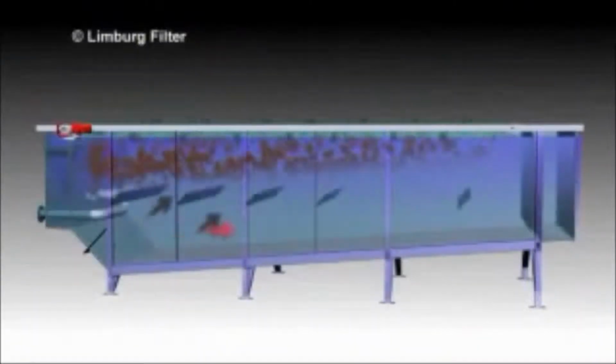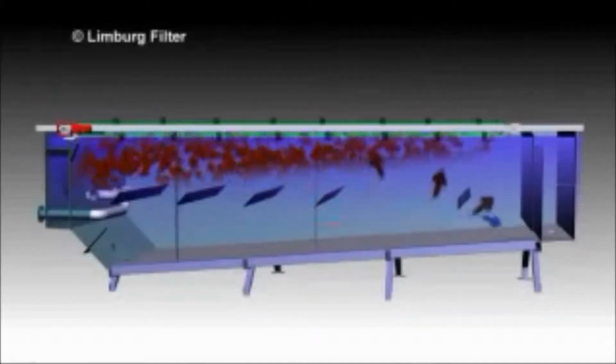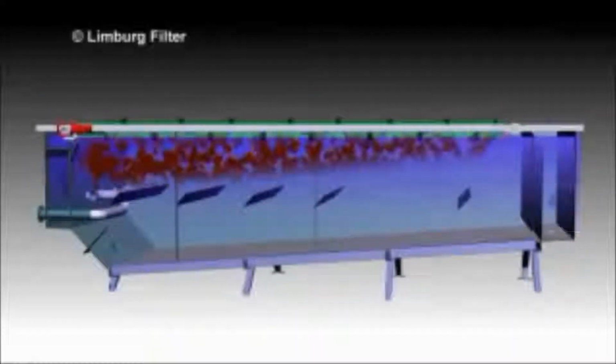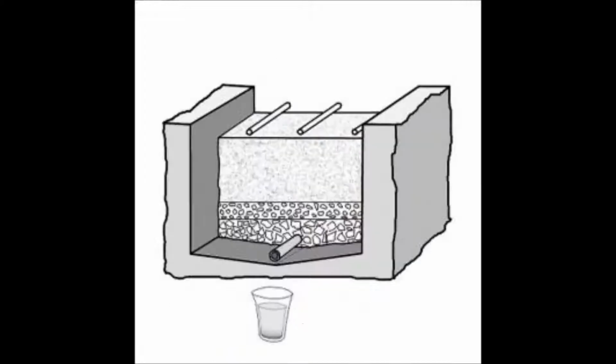Meanwhile in the dissolved air flotation clarifiers, water has air bubbled through it which becomes attached to the solids, which then rise to the surface where they are removed as waste. The water from these two processes is then mixed together before going through rapid gravity sand filters. The filters improve the clarity of the water further. Solids that build up in the filters are removed by backwashing the filters approximately every day. In the filters the pressure loss due to the filtration process is modeled dynamically based on the build-up of solids.